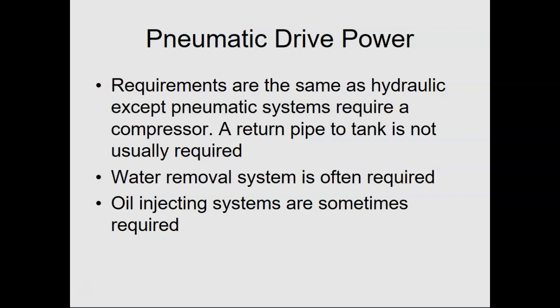So we have to have some form of a water removal system in pneumatics because otherwise you will end up with rust all over every component in it. You also have to inject oils back into it to lubricate your cylinders and such. Because if you don't do that, you're going to end up with a lot of wear and tear on them. That's the good thing about hydraulics.